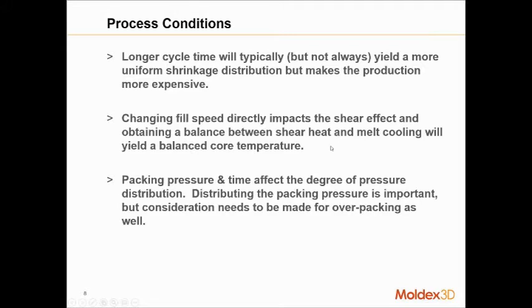All right, changing the fill speed directly impacts the shear effect, and obtaining a shear balance like we looked at in the runner system earlier, and a melt cooling like we discussed earlier with the mold design, will yield a balanced core temperature. So this is one of the effects that we really want to highlight, is that there's two main regions of temperature in your part.